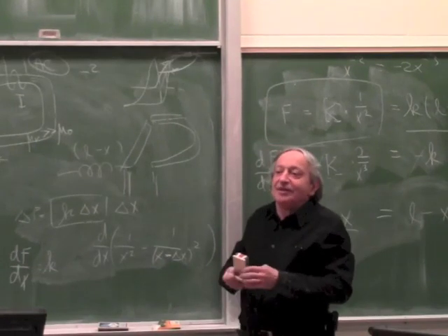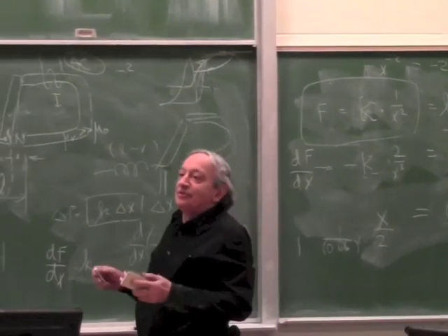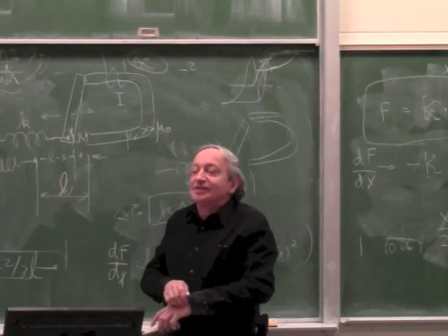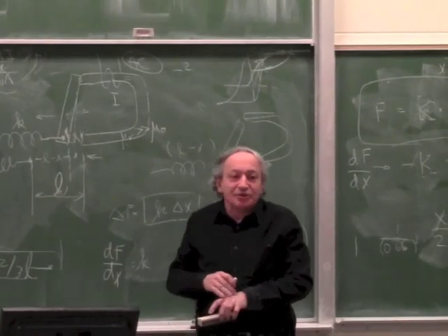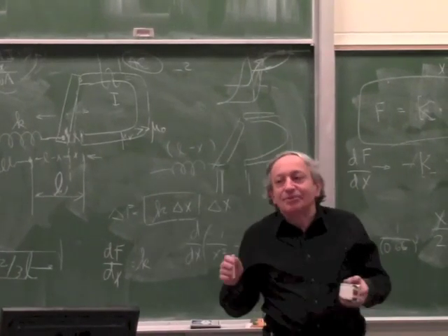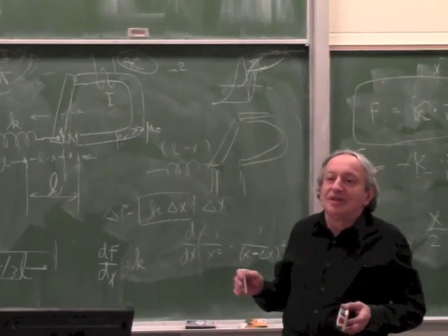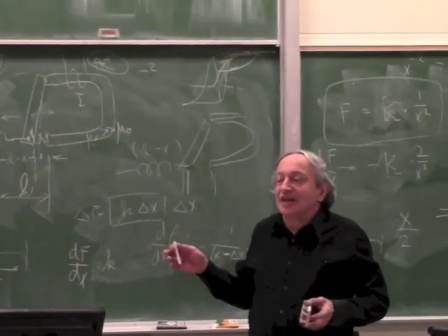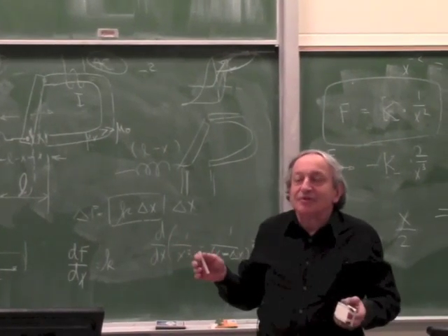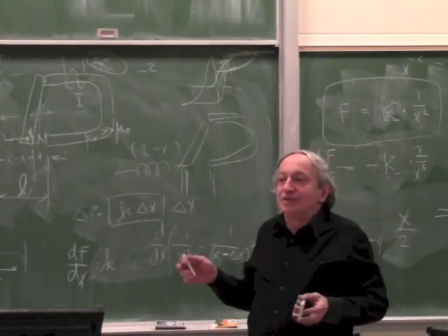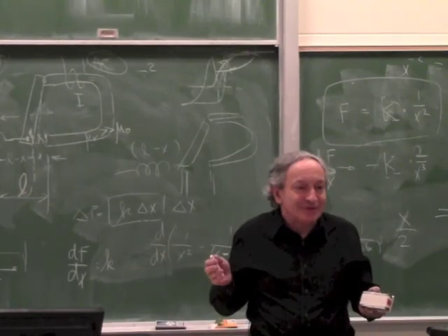So bottom line, if you really want a good servo, you can't use moving iron, except in situations where you have no choice. Because sometimes there are some reasons. For example, you need like infinite overdrive. Moving iron, you can overdrive it to infinity, it will just saturate, nothing bad will happen.